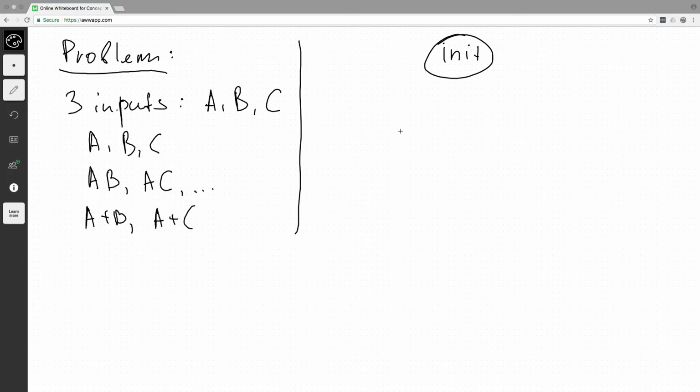The Moore finite state machine, the one that we are considering right now, we'll assume that for every combination here we have to introduce our own state, and the finite state machine will go to that particular state upon change of input condition. Let us try to identify those states.